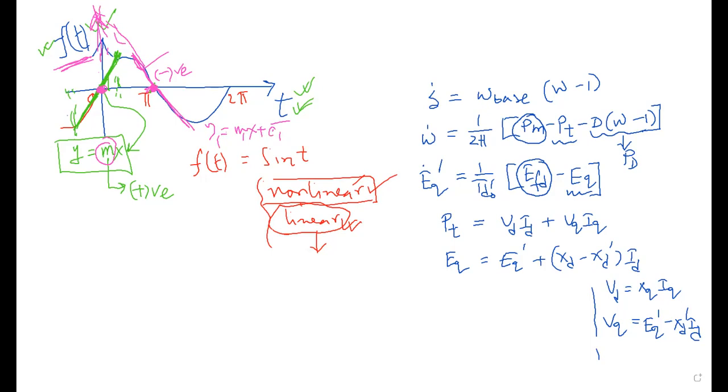The behavior, or the expression, of these two are different; their slopes are different. Later on we might find that for a stability-related analysis, this choice of equilibrium point is very, very important. That's why fixing an equilibrium point for getting a linearized version of an original nonlinear system is very, very important.